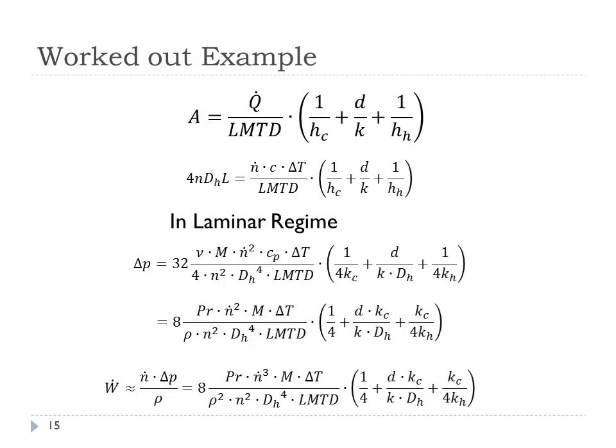So you can see once again there's going to be some kind of optimal value of the log mean temperature difference, because you can see the overall amount of exergy destruction looks like it's going to have some term divided by log mean temperature difference plus some other constant multiplied by the log mean temperature difference, and basically optimization of x plus 1 over x, you find that there's going to be an optimal value.